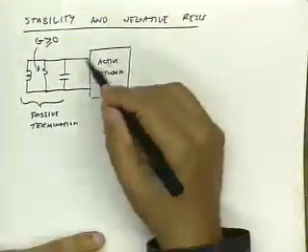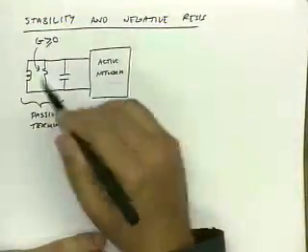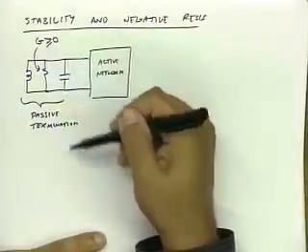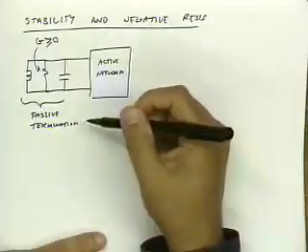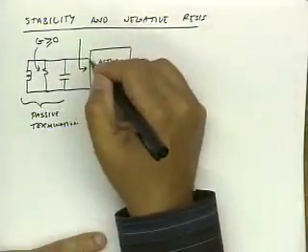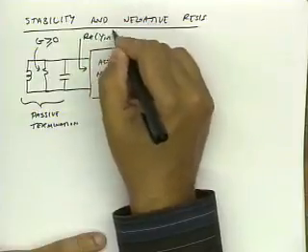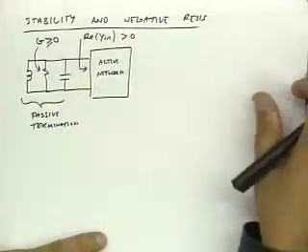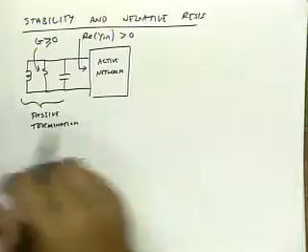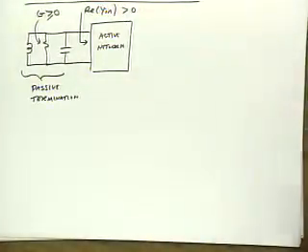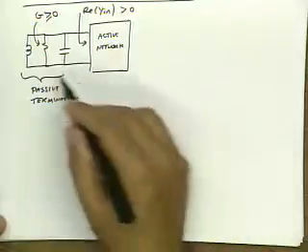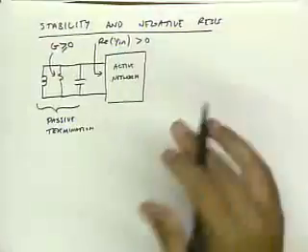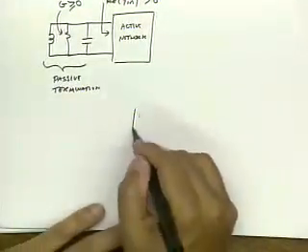And what I want is that under this condition, nothing should happen if this is stable. If I start observing oscillations here, then this is not stable. And what I'm going to show is that this is related to the real part of y in. If we can show that the real part of y in is bigger than 0, then this is stable. So this is a one port, and it's actually quite trivial. I won't even prove it because it's so trivial for one port. So let's see what happens for a two port.